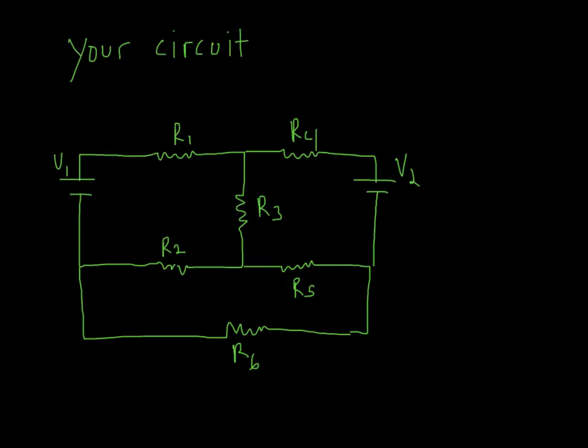Okay, your circuit's going to look something like this, where you have 6 resistors, and there's just something I wanted to point out when you simulate it on Multisim software. First, you'll put in the values that are in the lab, and invariably you'll find you cannot find the resistors you want to find in the lab, and so you'll substitute other values. That'll be the same for capacitors, inductors, for some of the other components.